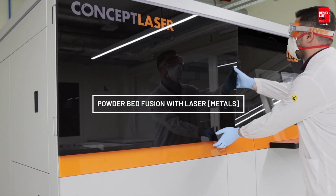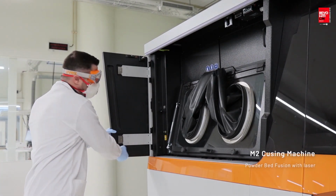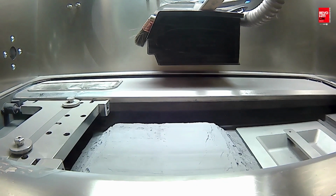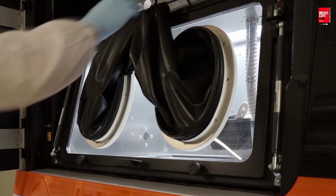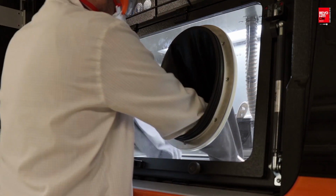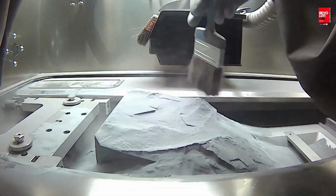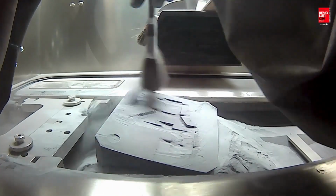Another technology that we have inside is the powder bed fusion with laser for metals. In our case, we are using aluminium, and after we made the data preparation, we start the production. After the production, all the frame and the sample are removed from the machine, and inside we should remove all the powder that will be reused in the other production. So we make the recycling of the material.